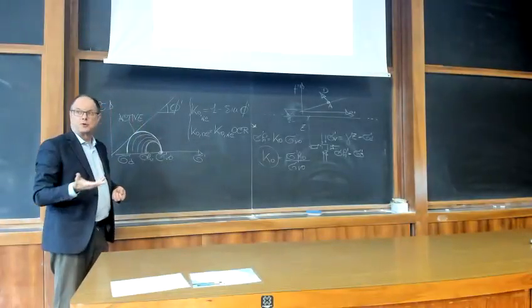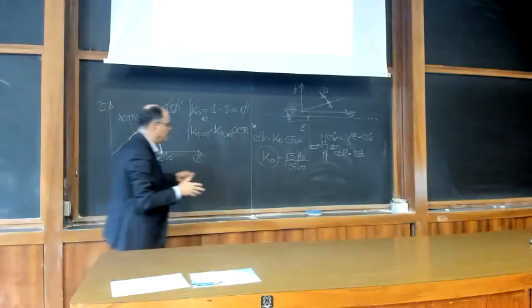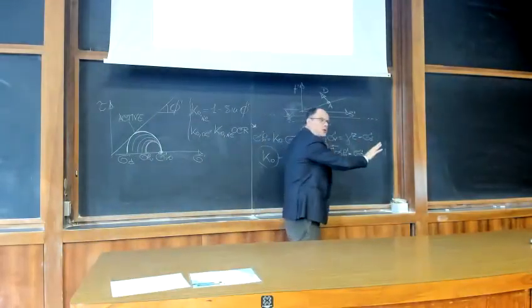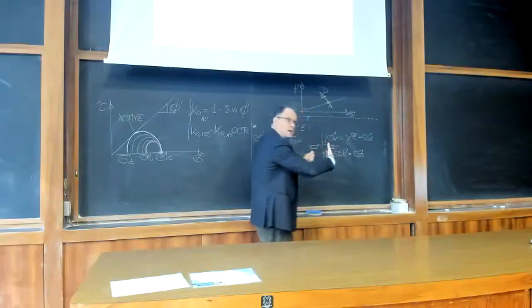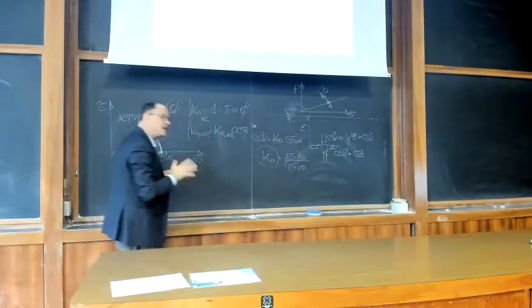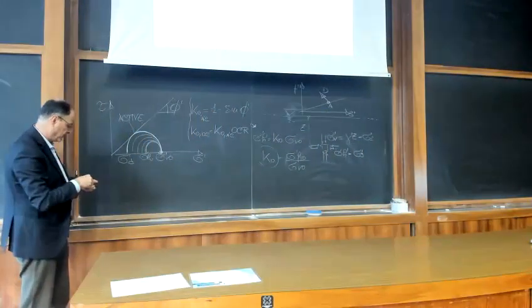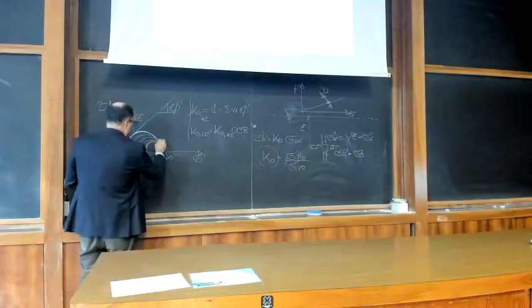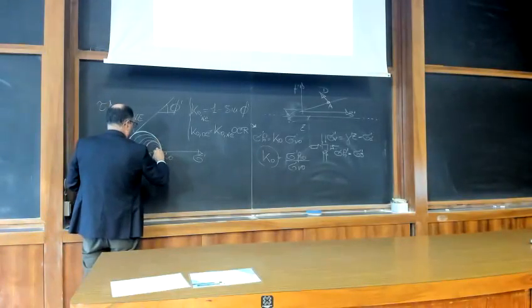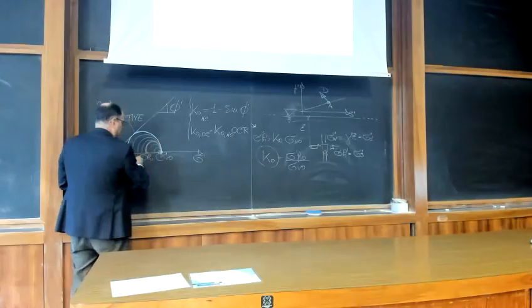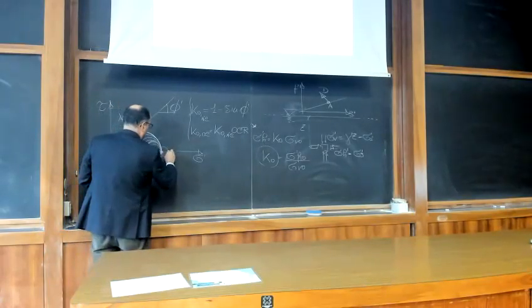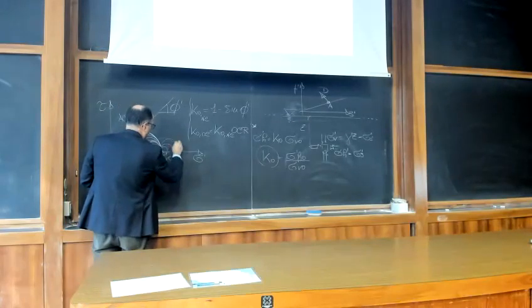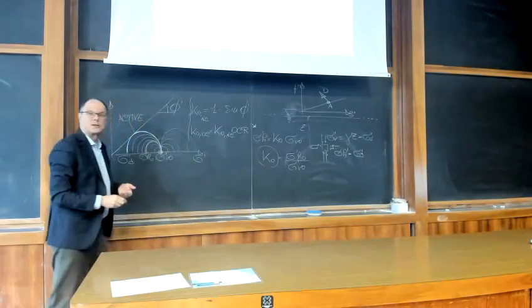You increase your horizontal stress. So let's assume that we push against the soil element, both sides. So we compress the soil element and we increase the horizontal stress. So we start from here, we reduce the circle because we increase the horizontal stress, then we go the other side and we keep increasing the horizontal stress once again.